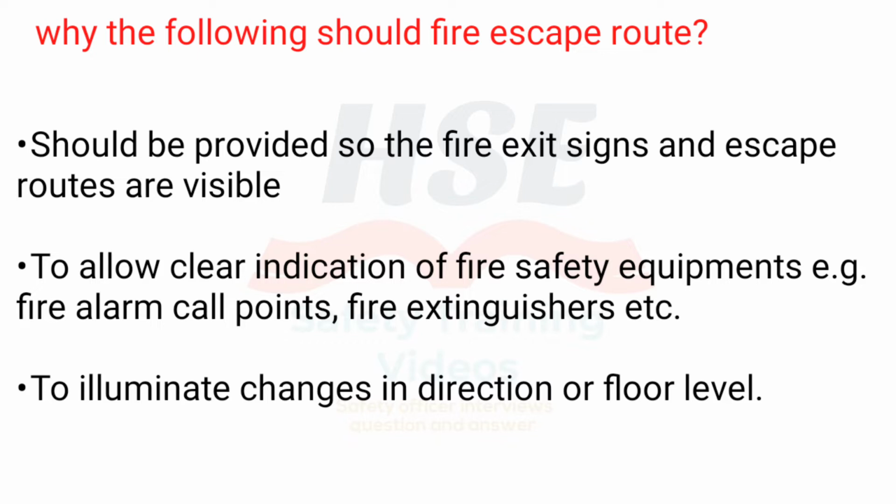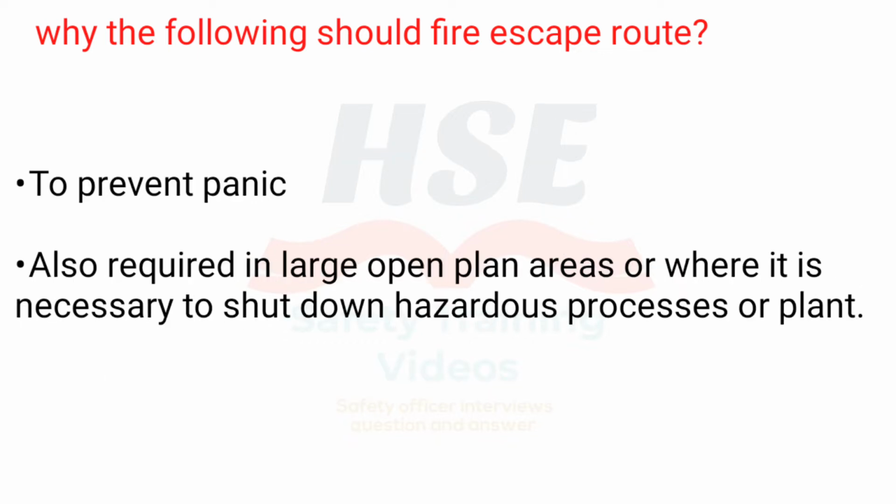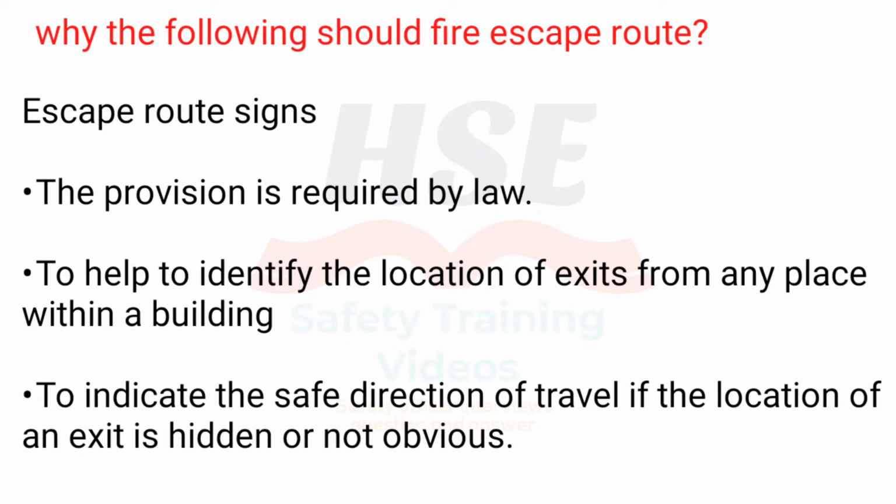To allow clear indication of fire safety equipment, for example fire alarm call points, fire extinguishers, etc. To illuminate changes in direction or floor level. To prevent panic. Also required in large open plan areas or where it is necessary to shut down hazardous processes or plant.